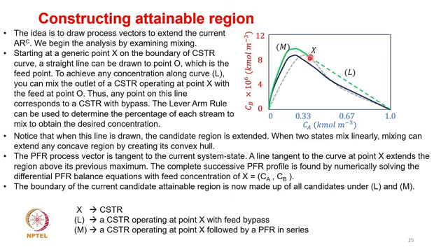Okay, at X it's a CSTR, and at L, if you want to operate over here, of course, you would have your own requirements. So if you want to operate over here, it is a CSTR at a point X with a feed bypass, because it is just a mixing, and this side it's a CSTR.